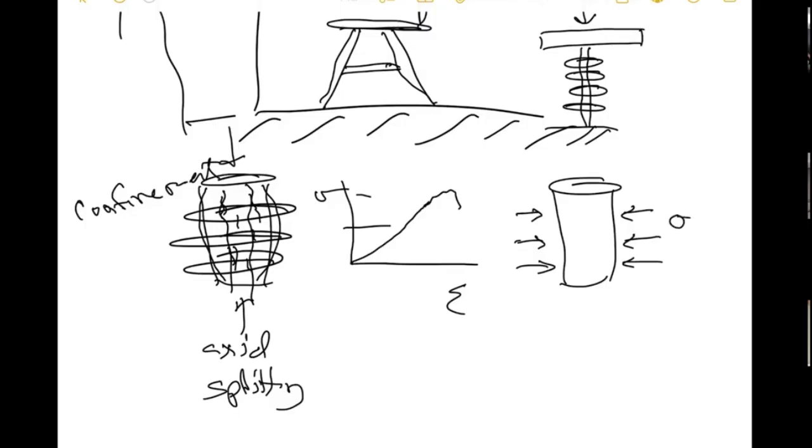Confining pressure, sigma prime, and this is now P. The way they do this in a laboratory is they take a cylinder of rock and they have a synthetic membrane, like a balloon, and they put the rock inside the membrane, and then they make a special cap, that's the platen, above and below, and then they hook the membrane to the sides, so it totally surrounds the rock. And now, as far as the rock is concerned, its boundary condition is what I drew.